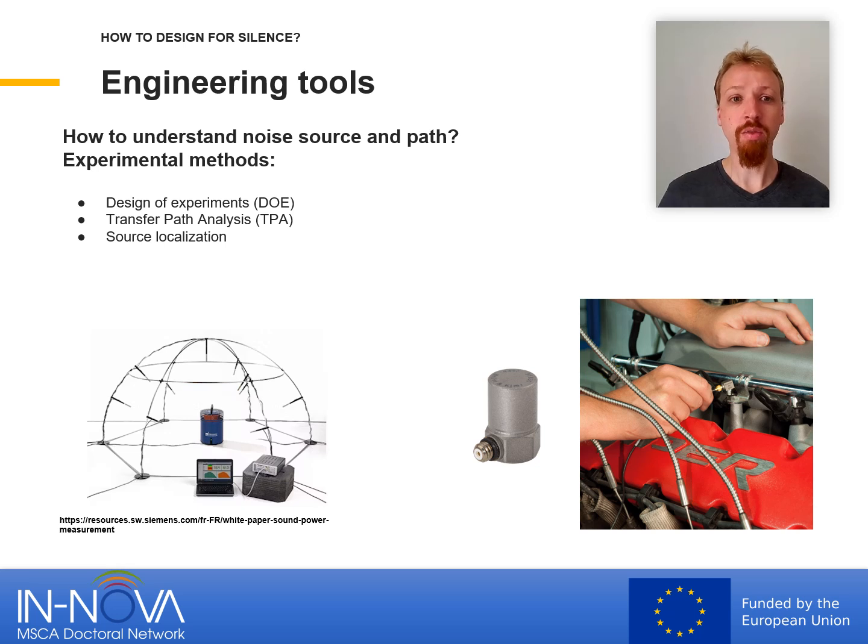There are plenty of methods that you can apply. I'll just give some ideas. You can do a design of experiments where you change your product and you measure the pressure or the vibration of your product, and then you can identify what are the most significant designs that improve or make the noise issue appear.